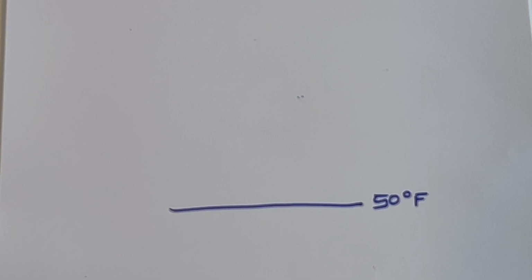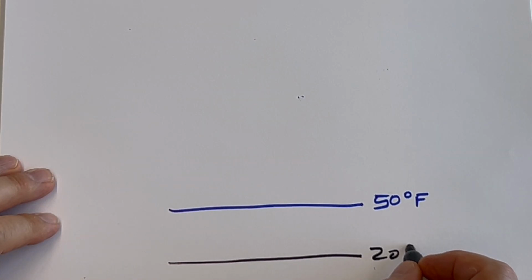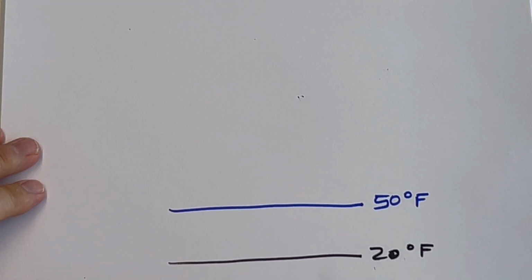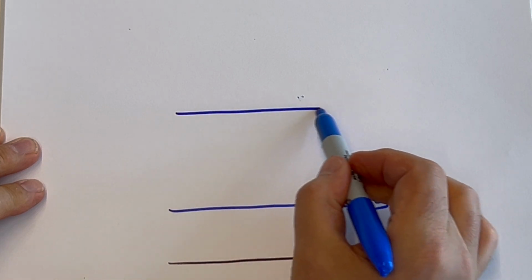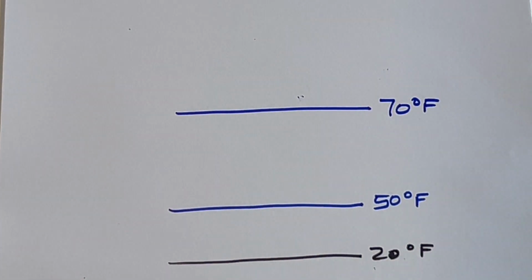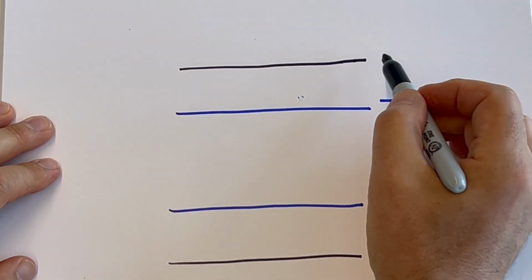It might be December, but the ground is warmer. We use our rule of thumb, we subtract 30, and the refrigerant will be at about 20 degrees Fahrenheit. And now we're going to use this as a water-to-air heat pump, and we're heating indoor air at 70 degrees. And we use our rule of thumb, and the refrigerant will be 30 degrees warmer than that.